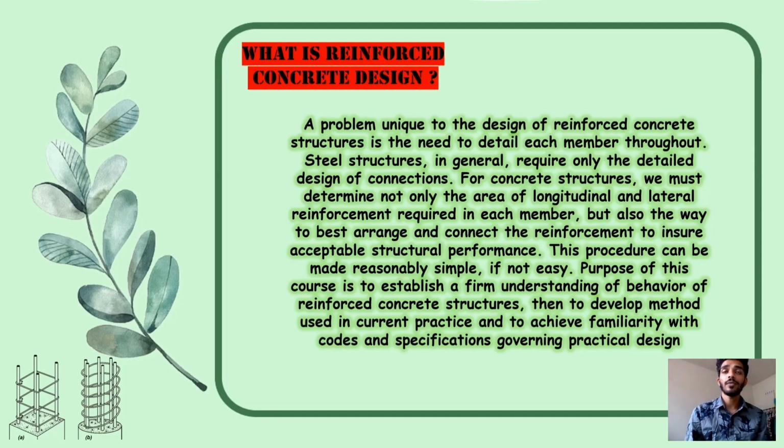Now in this slide we are able to see the meaning of reinforced concrete design. A problem unique to the design of reinforced concrete structures is the need to detail each member throughout. Steel structures in general require only the detailed design of connections. For concrete structures we must determine not only the area of longitudinal and lateral reinforcement required in each member, but also the way to best arrange and connect the reinforcement to ensure acceptable structural performance. This procedure can be made reasonably simple, though that is not so easy.